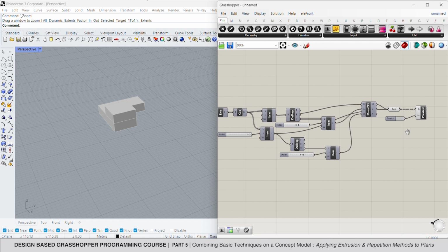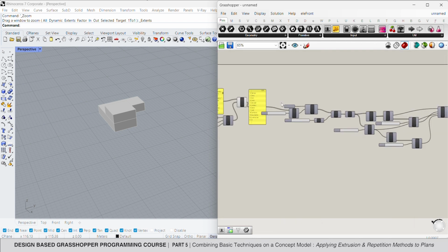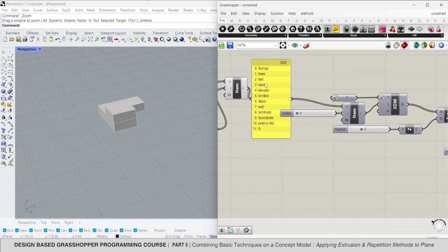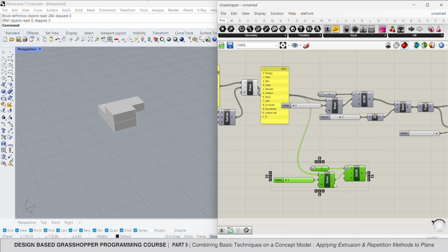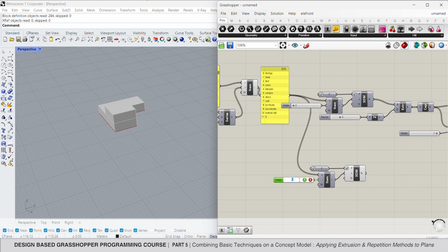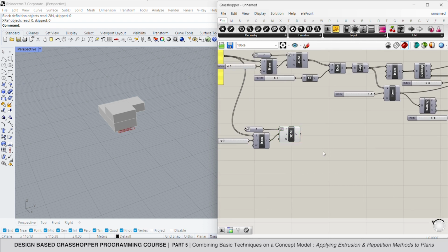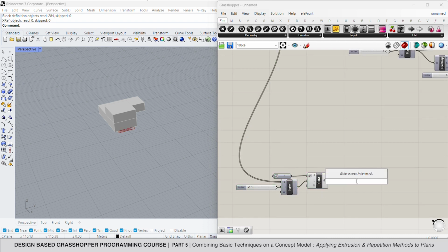Same way, we can learn how to create a staircase based on the 2D drawing. So let's copy the import command and take 3 as the layer number. I want to create a solid surface, then divide that based on the predefined steps.